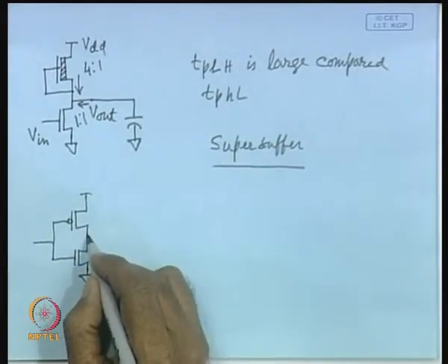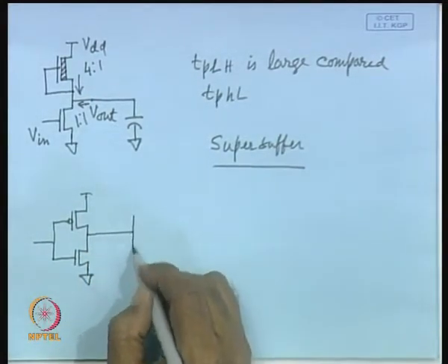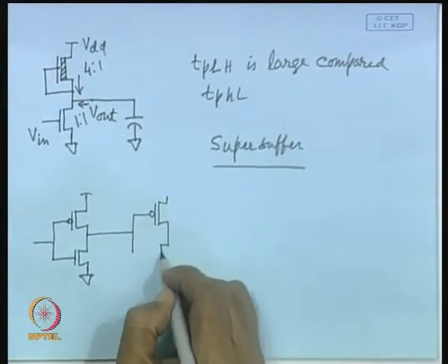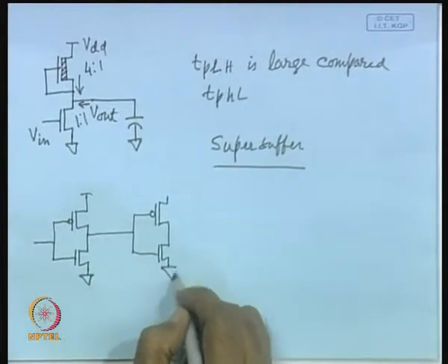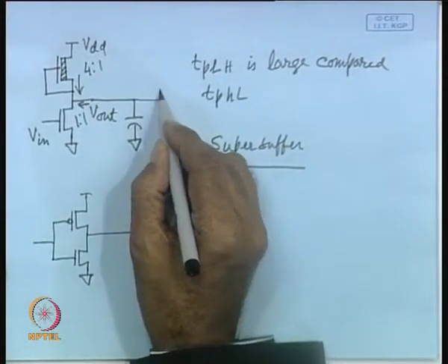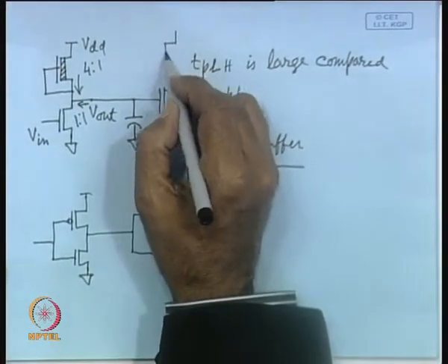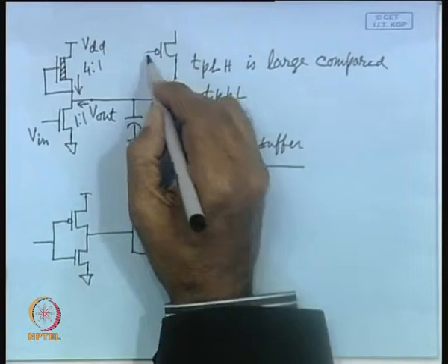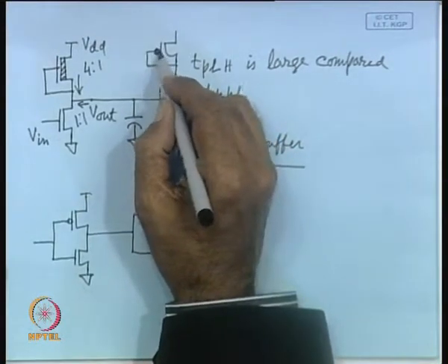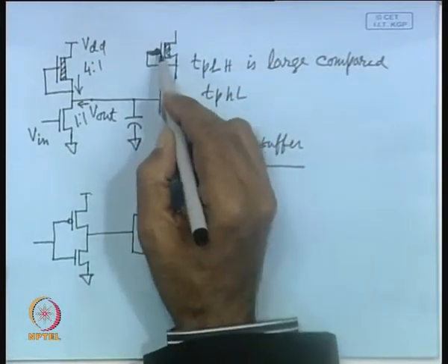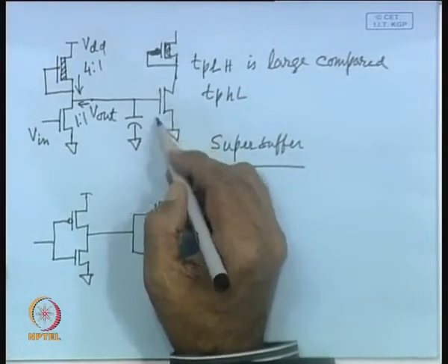So, that is the advantage of CMOS inverter, but unfortunately what happens whenever this is driving another stage, you can see here the capacitance is quite large compared to NMOS, because in case of NMOS this stage will be driving only the NMOS transistor. The PMOS transistor, if it is an inverter, will be like this. So, it will go to only the gate of the NMOS transistors.